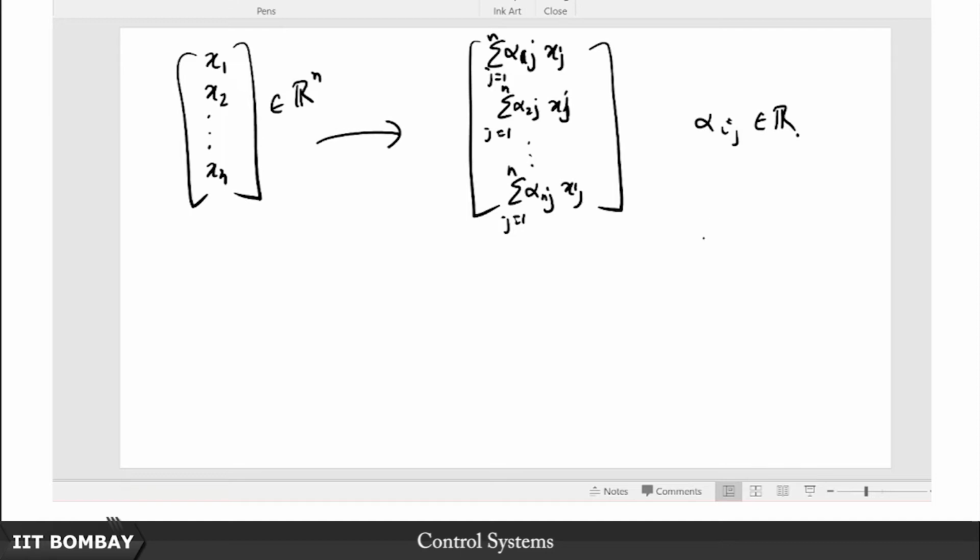are real numbers. Okay. So, suppose you have been given a set of n states, which, remember what states are, they capture the memory of the system, right. So, there is actually an engineering common sense reason why we chose the output of those integrators as states: the integrators are basically the memories of the system. Whatever has happened to the system up until the point when I begin my observation, which is t0, is captured by these states. So, I do not need to worry about what has happened in the past, so long as I have information about these states at that instant t0, that is what defines a state, right.